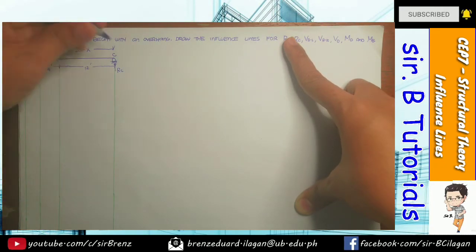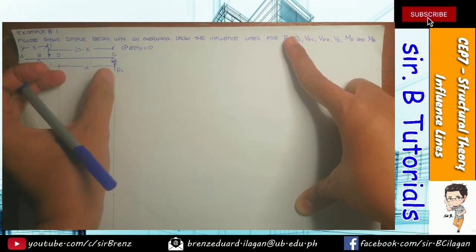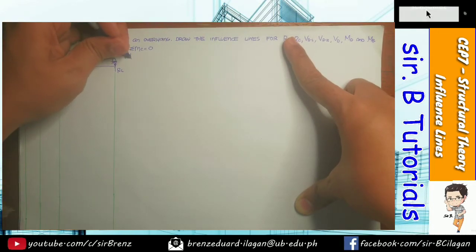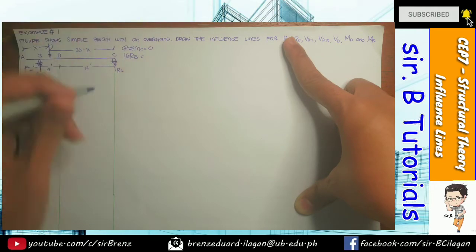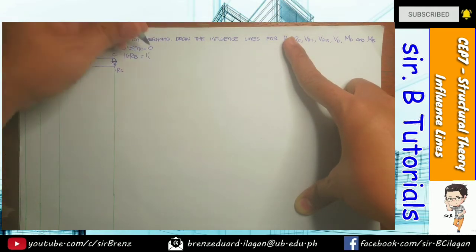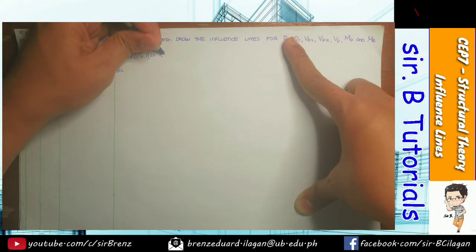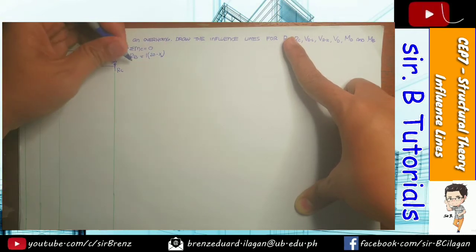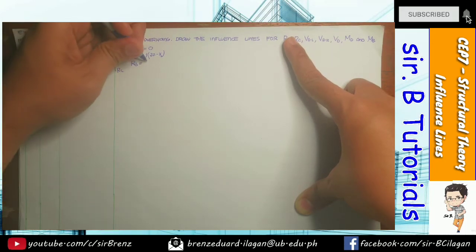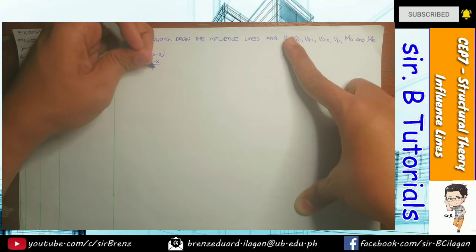So, by taking summation of moment at point C equals to 0, our equation will be 12 plus 4, so that is 16, RB is equal to 1 times 20 minus x. Therefore, our RB will have an equation of 20 minus x all over 16.